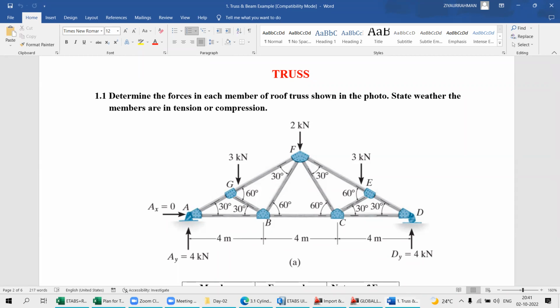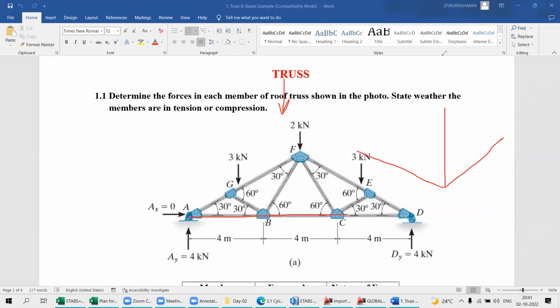Okay, let me explain first. Here, I am going to look at this model from the top. So from the top, this is the X direction. Two planes will be there, along the Z direction. ETABS considers the horizontal direction as the x-axis, the other plan direction as the y-axis, and over the height it considers z. So in plan, the directions are x and y, and over height it is z.